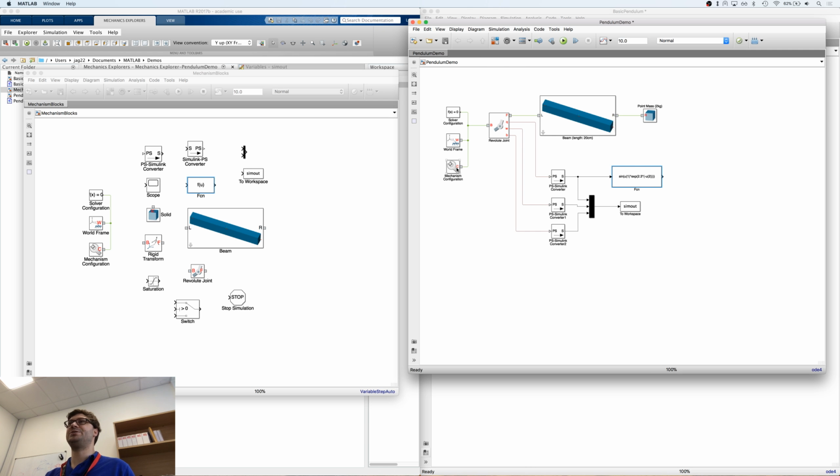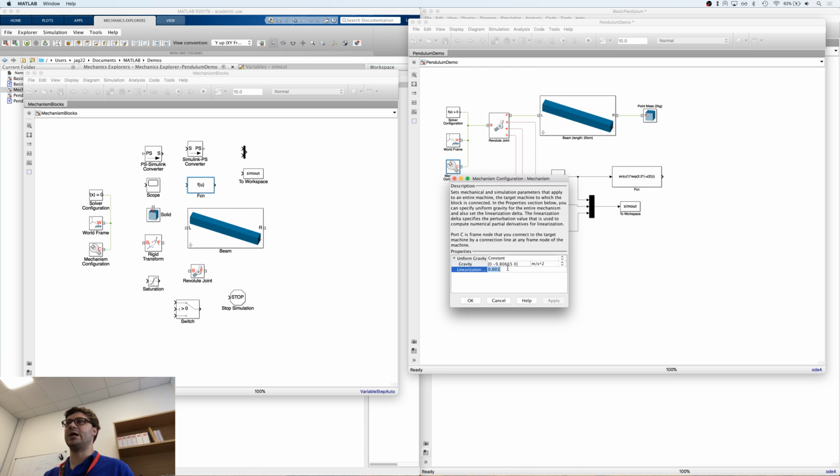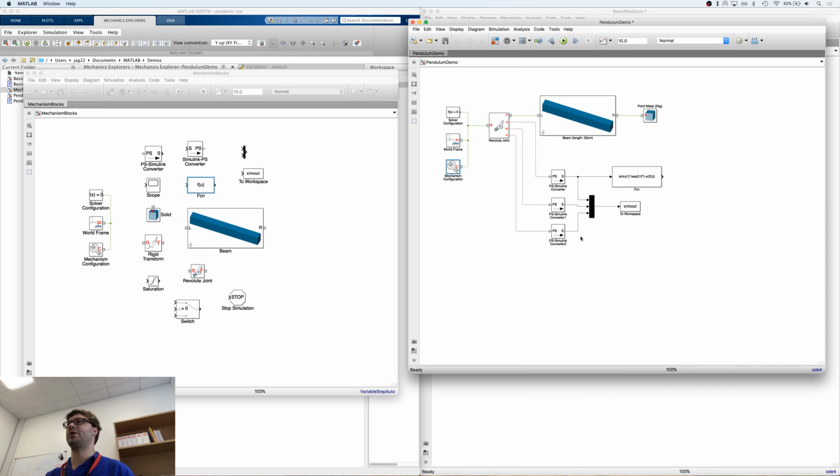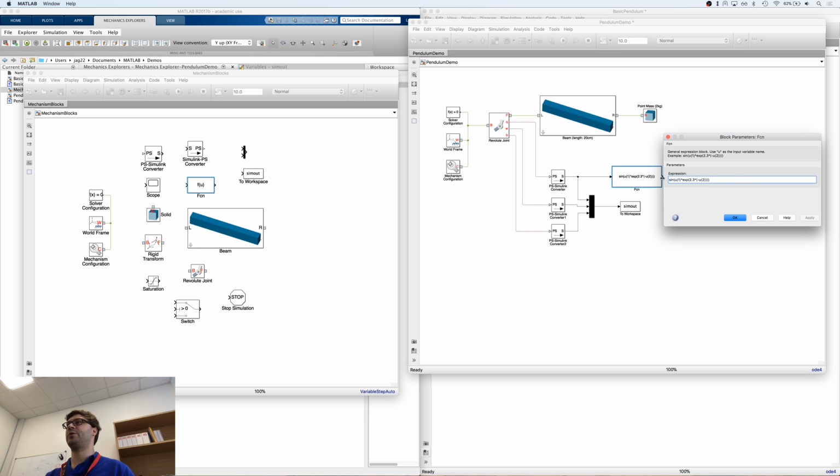The first thing we need is gravity, so we need to resist this gravity. So we need that value. Okay, copy and paste that. It's going to be gravity times the distance of the beam, so 0.2, remember it's in SI units, times your point mass of 2. And we also have to know the angle at which that mass is at.